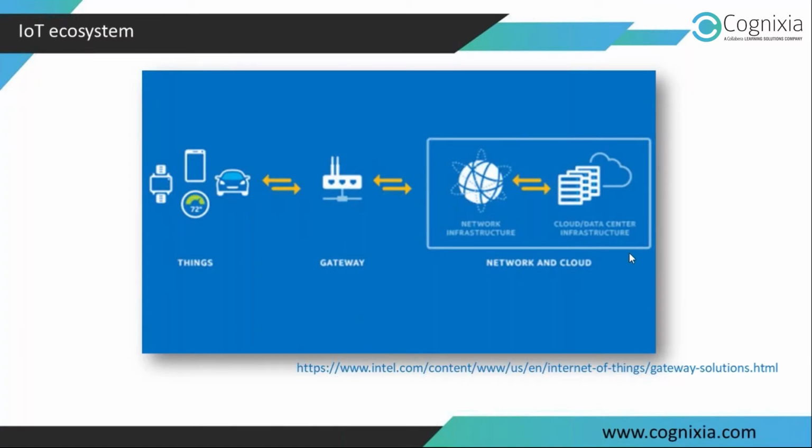So Mohammed, I just pointed this out. One of the roles a gateway plays is protocol converter or enabler. For example, if your device is a Bluetooth device, if it is using Bluetooth to communicate with other devices, obviously Bluetooth is not an IP capable technology, right? So in that case you would need an intermediate node which could help your Bluetooth device to connect to internet. Okay, so one of the roles gateway plays is it's an enabler or protocol converter.